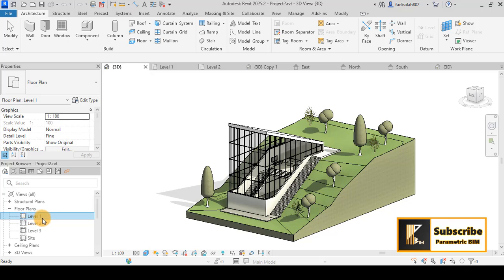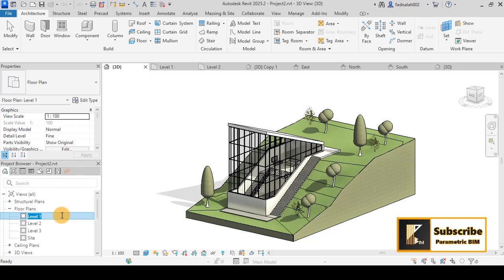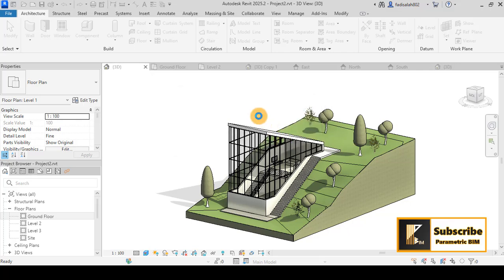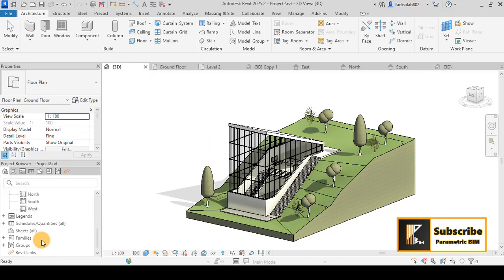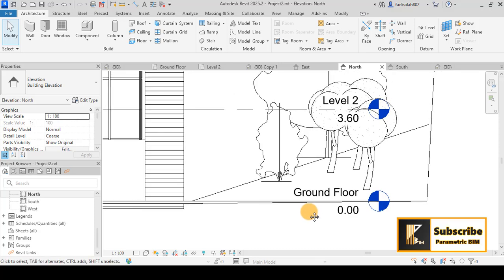has the name of level 1, but I can control that. If I want to change it to another name, I can right click and then go to rename and rename it as I want. For example, ground floor, basement floor, first floor, as you want. And when I click here, it will give me a message asking would you like to rename the corresponding level and views? Let's say yes. So if I click yes and I go to, for example, the elevation, you can see that the level in the elevation and the section and any view associated to this level will be named ground floor.